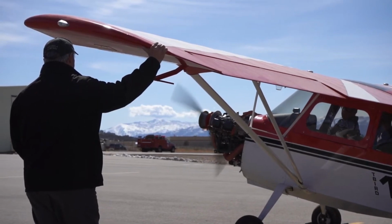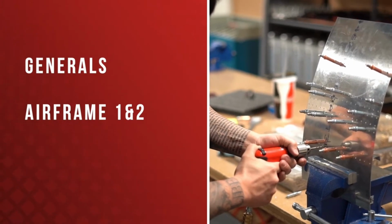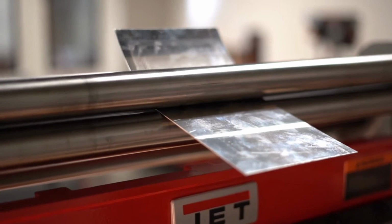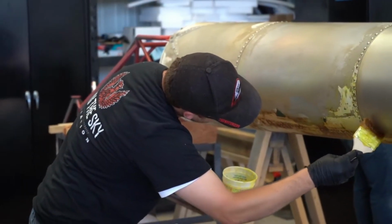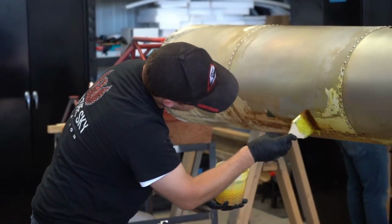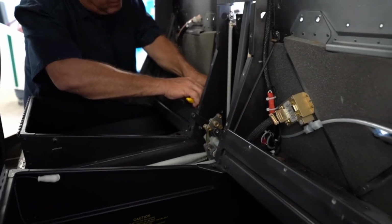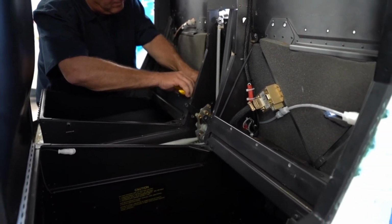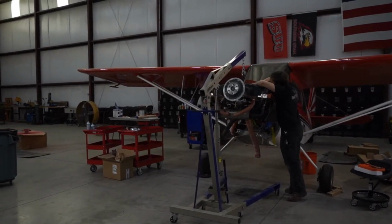6. Except for holders of a sport pilot certificate, the holder of a pilot certificate issued under Part 61 may perform preventive maintenance on any aircraft owned or operated by that pilot which is not used under 14 CFR Part 121, 129, or 135. The holder of a sport pilot certificate may perform preventive maintenance on an aircraft owned or operated by that pilot and issued a special airworthiness certificate in the light sport category. 7.